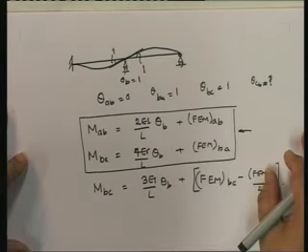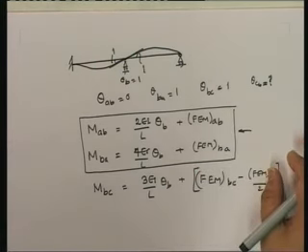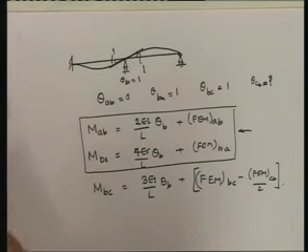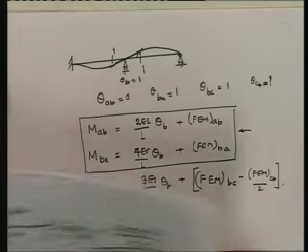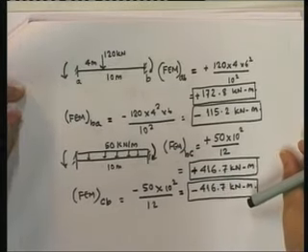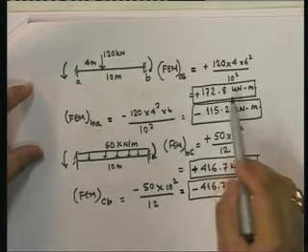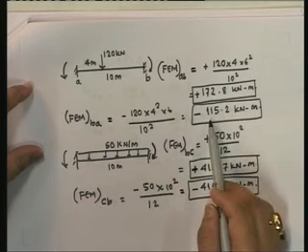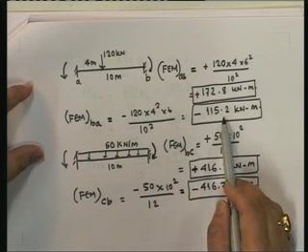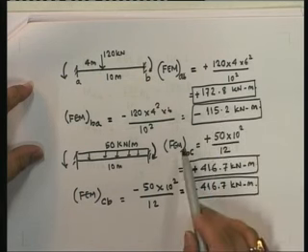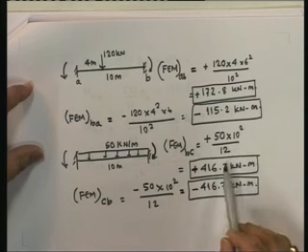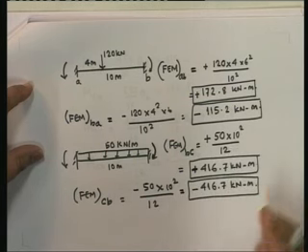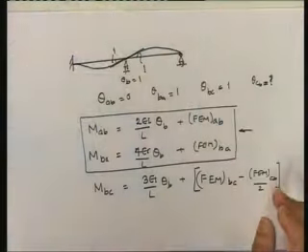Now I need to find out the fixed end moments for AB and BC, and note that I have already done those earlier, so I am just going to show you that. We have already evaluated these. The fixed end moment AB is equal to plus 172.8, the fixed end moment at BA is equal to minus 115.2, and the fixed end moment BC is equal to 416 and CB is minus 416. So having done that, I can plug in those values directly. So what do I get?